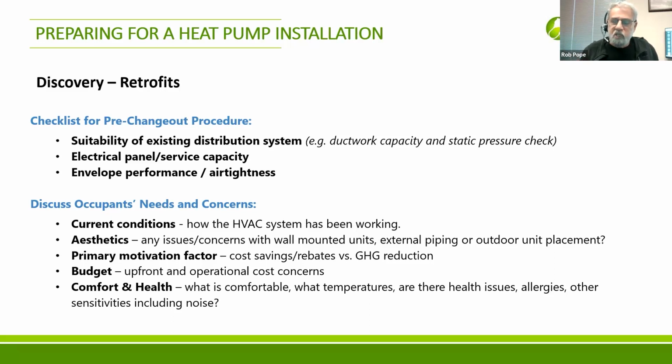The most common issue is ducting is not sized adequately. It's not big enough, right? There are things you can do about that, but you've got to check that. That's really important. Then there's electrical panel capacity. You might have a 100 amp service, but now you need another 40 that you didn't have before. Maybe there's room on the panel, maybe not. You really got to check that out. It's a big deal.